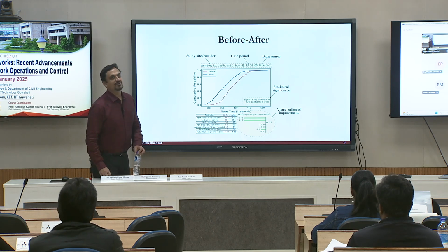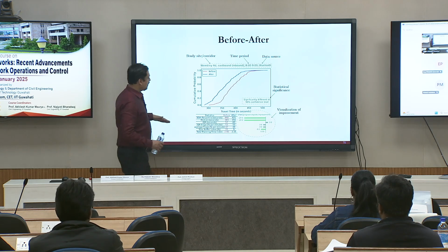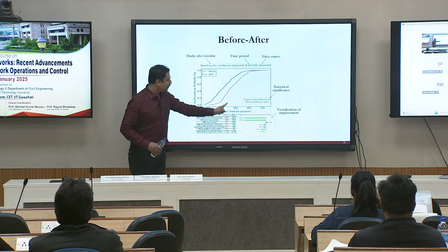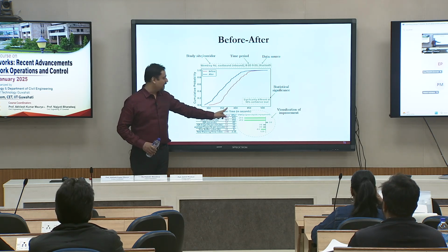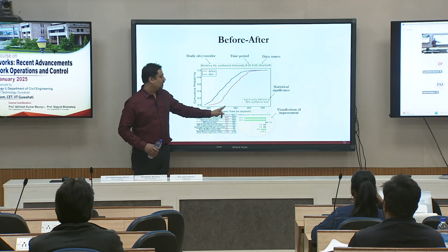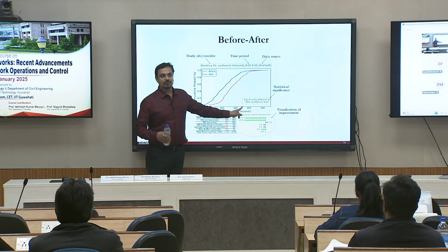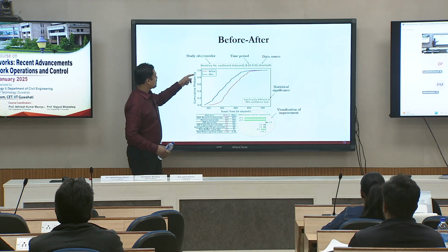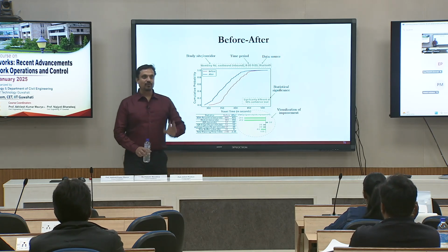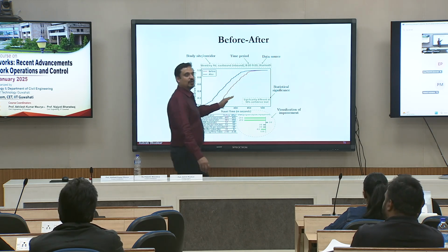How do we read the cumulative plots? Let's first read a cumulative plot. So cumulative probability means how? If I look at this one, 0.4, so 40% of your observation on that day had a travel time less than, let's say, 370, right? 80% of the observation on that day have a travel time less than maybe 430, and obviously 100% had a travel time less than 500 seconds, more or less both of them, right? That's one way of looking at it. So cumulative plot tells a lot about what's happening just in one view.